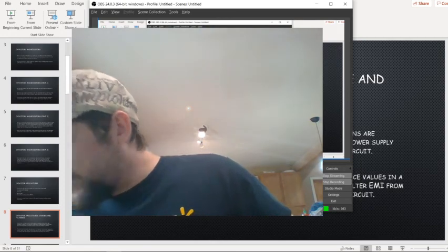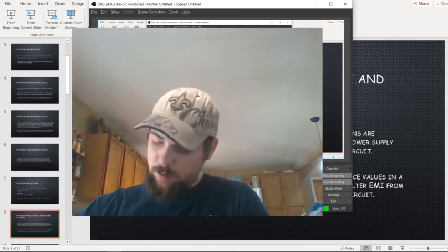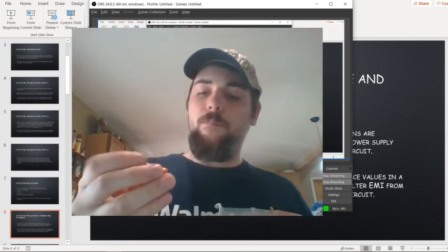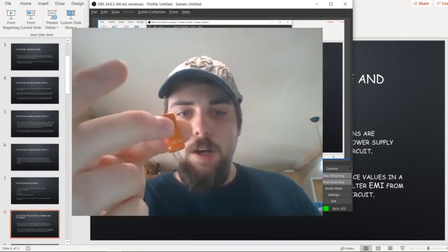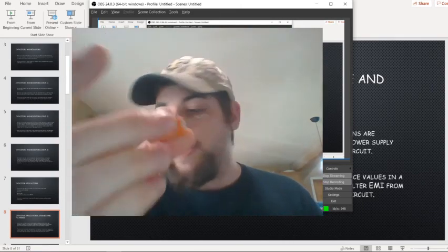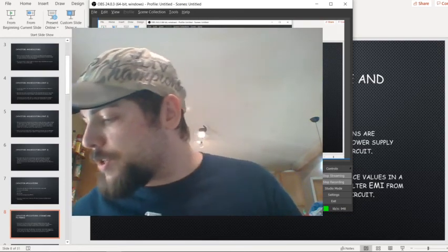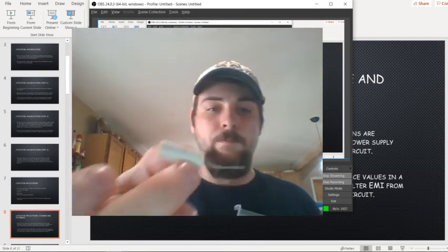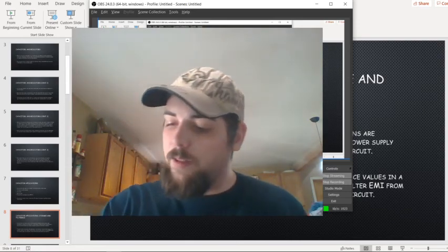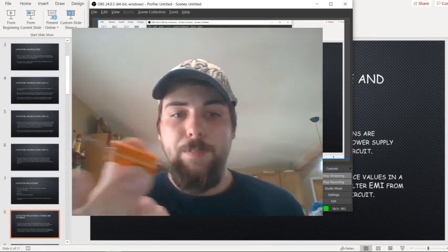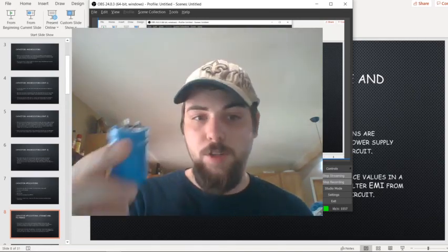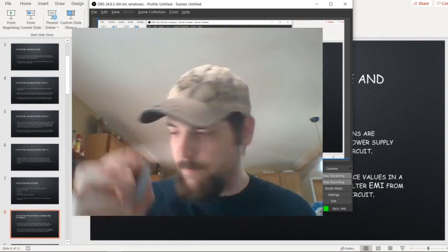More high Q, what's this one? Nichicon. Now, if you notice, this one's kind of an oddball because it's what's called axially leaded. And you see that more in film capacitors, like this one. This one's a film capacitor. We'll get to those. But this is also an electrolytic capacitor. This is what's called an aluminum electrolytic capacitor, and so is this one and this one.